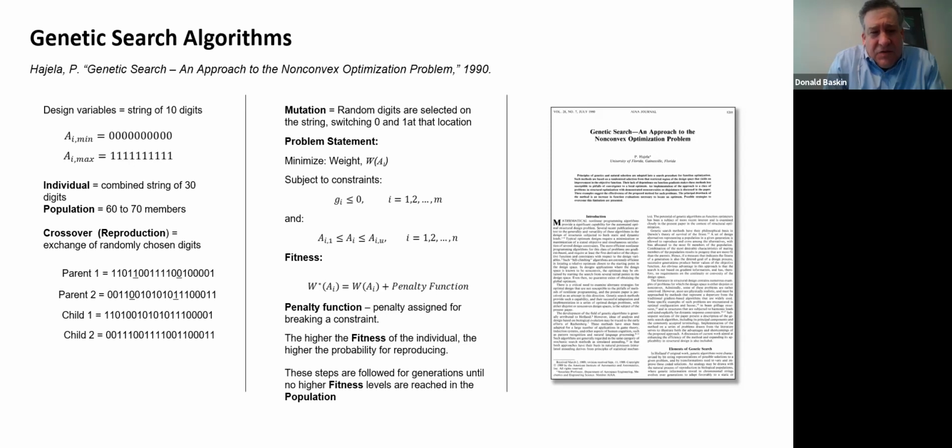With this method, you have a population, and this is really abstract. You have a population of different designs in your design space. You've got this individual who has this wall thickness, this individual that's got that wall thickness, another individual who's got a third wall thickness. Some complexity, some number of design variables, and you represent these individuals as a string of numbers, of zeros and ones.